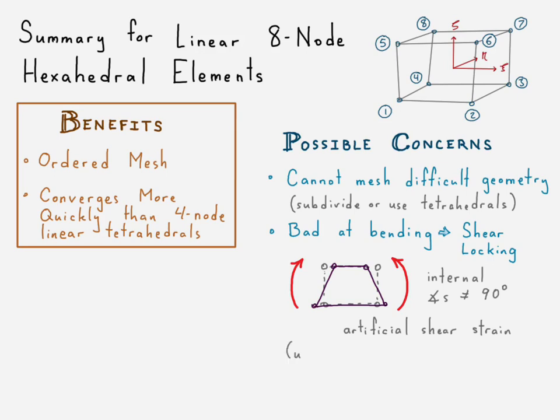Okay, so the solution is use quadratic formulation. And for the hexahedral element, instead of using the 8-node hexahedral element, you would use the 20-node hexahedral element.